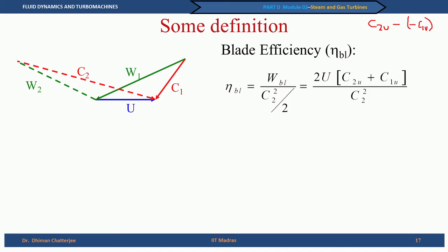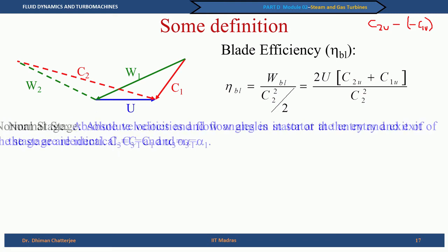In fact, let me also stress at this point that whenever you are solving problems where we need to find out velocity or the blade angles, it is always a good habit to draw the velocity triangle as accurately as you can and then work it out. That will always give you the confidence that your values are becoming realistic.